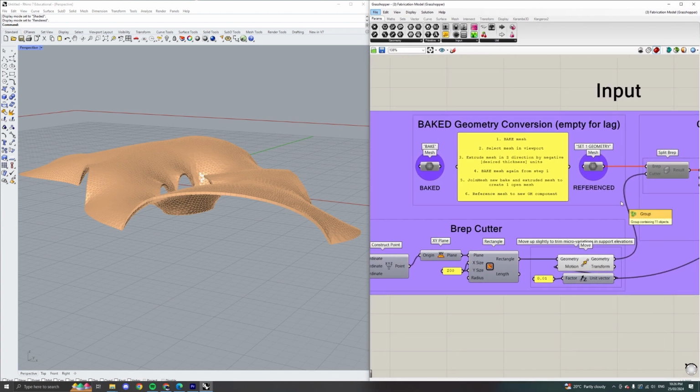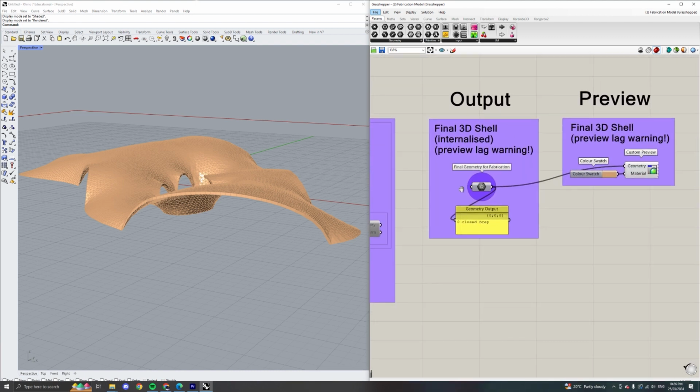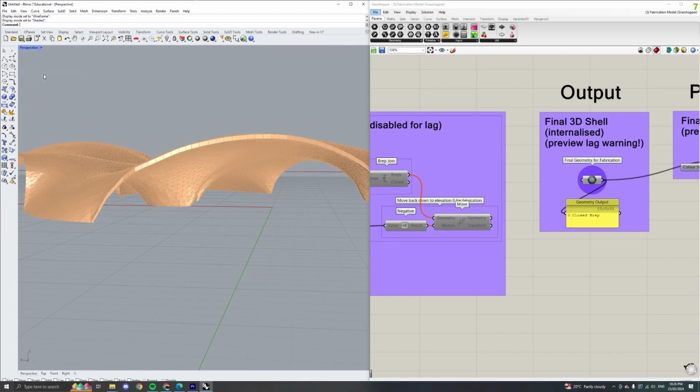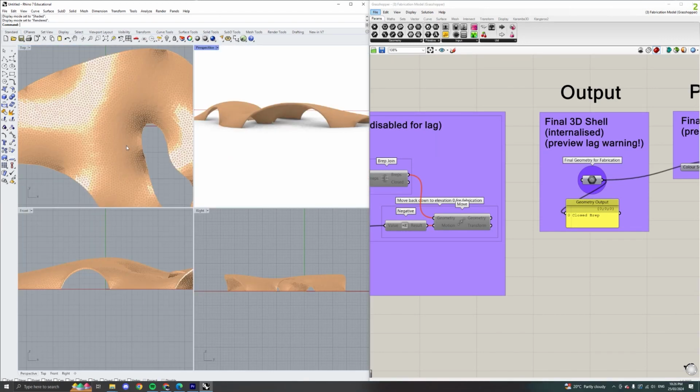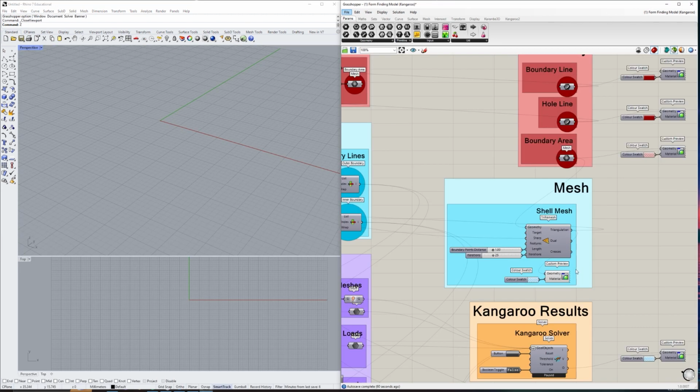With a refined wireframe mesh, we can create a 3D version of the form that we fabricated. This process will require manual modification to baked geometry, starting with the mesh, then extruding it along the Z-axis, then cutting its base for a flat bottom. From this, we now get a clean 3D geometry component contained as one closed object.